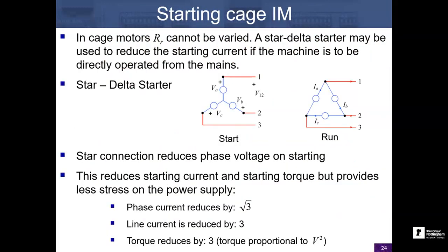And then the final part of the induction motor lectures was around starting and various performances. So there's a bunch of different ways that we can handle starting in induction motors. Some of them are quite simple, things like changing connection between star and delta. So this is something that's used in two ways. We can use it to increase the current through the three phases and get a high torque for starting. So if, for example, we want to start on a high load torque, we can use that to temporarily bump up our torque at starting.